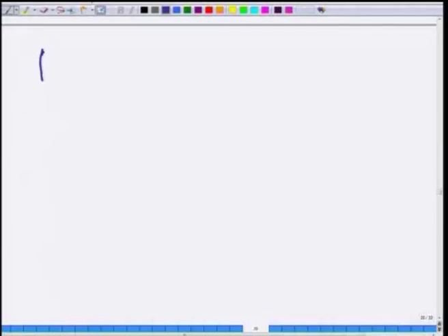Then we moved to pipe flows. We discussed that when we did the simple laminar solution of flow in a pipe, the relationship between pressure drop and flow rate that we got was not valid for all Reynolds numbers. It is valid only when the Reynolds number is less than 2000, when the flow is laminar. After that, the flow undergoes a transition from laminar to turbulence, and in that context, if you want to solve problems in engineering fluid mechanics, it is not sufficient to know only the pressure drop flow rate relation in the laminar conditions. So, we have to go to turbulent conditions as well.